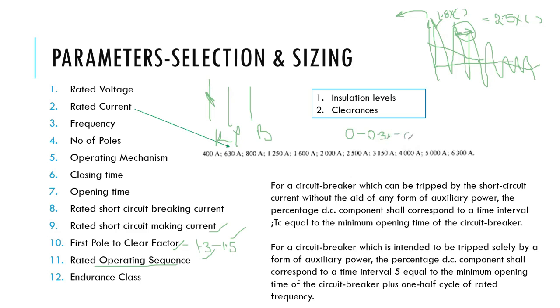The breaker can be closed, and the breaker can again be opened after 3 minutes. You can close the breaker, and again the cycle repeats. It seems that is the duty cycle of the breaker. I mean that you can operate the breaker in this cycle, like you can open the breaker and in the next 0.3 seconds, you can close. Again, you can immediately open.